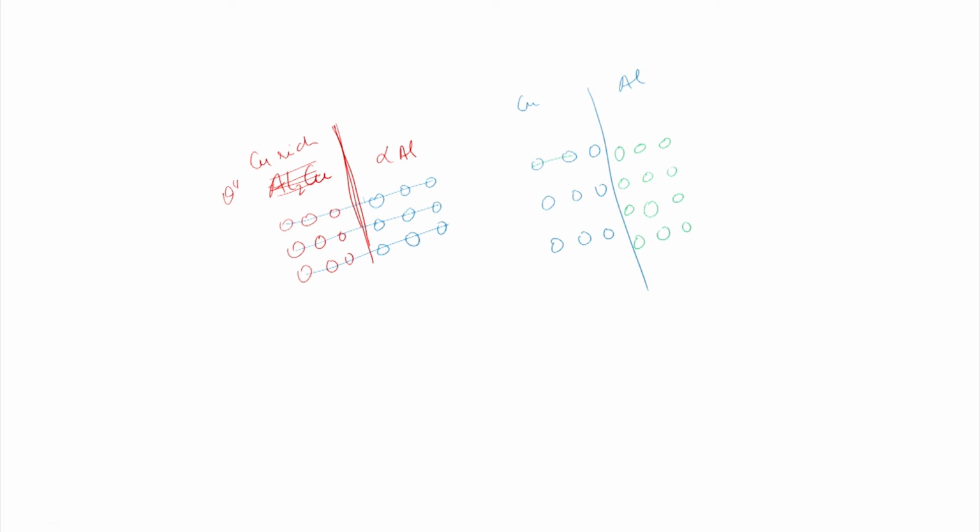Now, you can see that there is no continuous arrangement. If I see the arrangement here, there is some kind of mismatch. So now it is not a coherent interface, it will try to be an incoherent interface. In fact, it is going to take care of this misfit by maybe introducing one dislocation here. If it is introducing a dislocation here, then it is called a semi coherent interface. So, this is coherent, this is semi coherent, and in incoherent, in fact, you cannot have any relationship between the two.